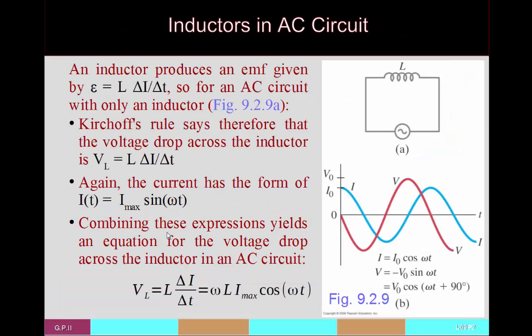In my previous discussions of inductors, I didn't do much with an inductor in a DC circuit. You'll notice that I talked about capacitors and resistors in DC circuits, but not really inductors. The reason is that an inductor is not very exciting in a DC circuit. It does one thing: if you first flip the circuit on or off, it can create a pretty powerful back current. But that is usually a temporary effect that eventually dies out, usually on a very fast time frame for most typical inductors, and then the inductor just acts like another piece of wire.